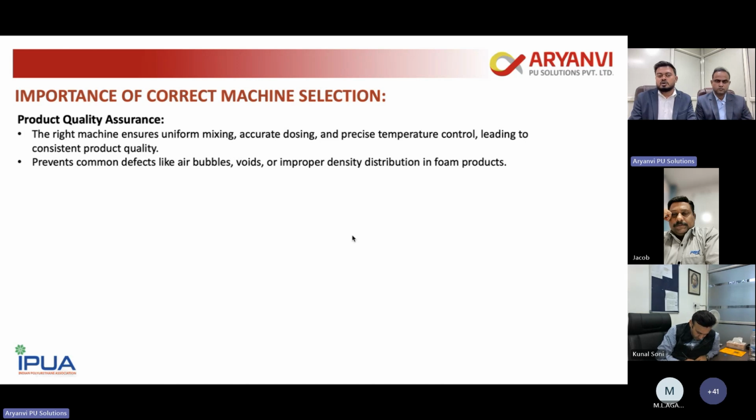So once they open the mold after the curing time and extract the product from the mold, they see air holes or air voids present in the product, which degrade their end product quality. So if you have the right configuration, again you will have control on this kind of thing on the machine.